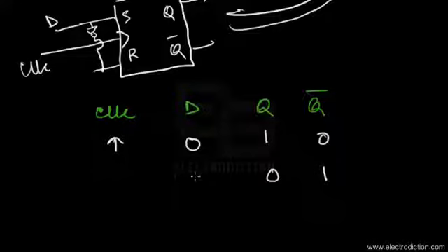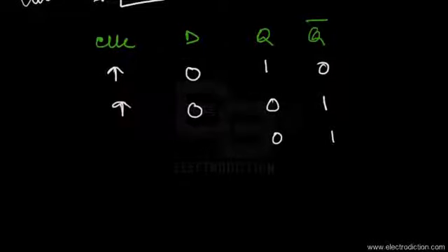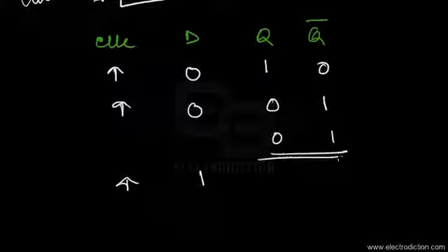If I maintain the input at D at logic 0 level, then Q would remain at logic 0 without any change. That's how this process occurs. On the contrary, if I put the D input at a logic 1 level, then if this was the previous state of our D flip-flop, it would be set in this case.